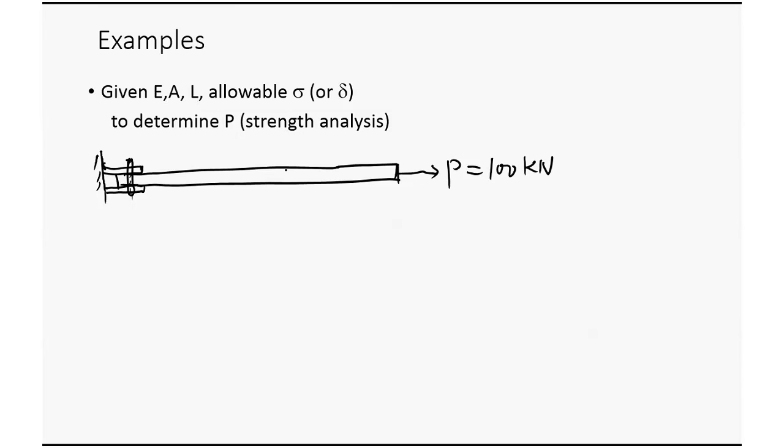All right. So I know the area of this cable. A equals, to make it easy, 2 millimeters squared. The length L is, let's say, 4 meters long. I'm just randomly coming up with a number. Young's modulus, let's say 200, oftentimes in gigapascals. It's very big. Let's say for the material, I know the yield stress sigma yield is 200 megapascal.